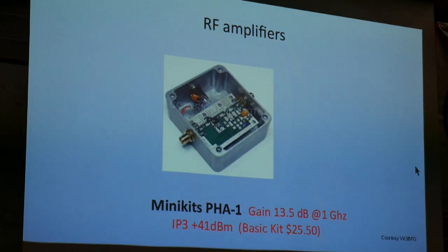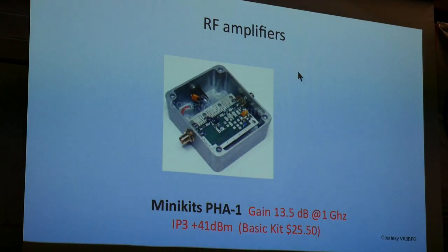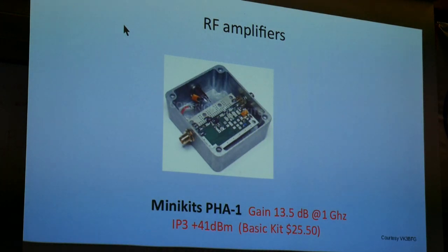Okay, so mini kits, they've got some good stuff. Of course, you've got to boost up your power, so jumping back to transmit again. These SDRs are typically only generating a milliwatt or less, so you're not going to get very far with that. That transmitter I've set up at the back of the club here is running about half a milliwatt. So it's probably going about as far as these trees here, and that's about it, I would think.